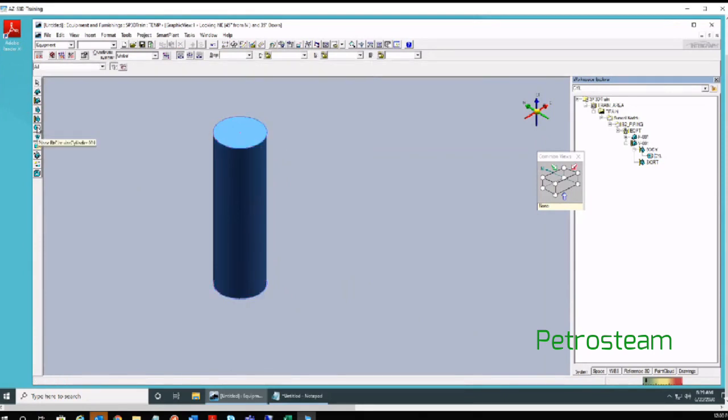So I'll go back here. Right now, the last used shape will be visible for you. Again, click here, wait for some time to give you all the options. And now this is your dish end shape available. I will select this dish end shape.